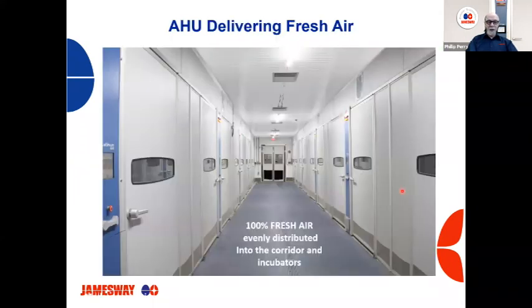Here's an example, just air being dispersed. There's no recirculation of the air. The machine is pulling into the intake what it needs, and again, it's being expelled. The stale air is being removed into the plenum. So, very good, like I say, to keep a clean environment, and there's not any introduction of any contaminants that one machine might have. You run less risk of introducing it to other machines in the hallway because the air is not being recycled.